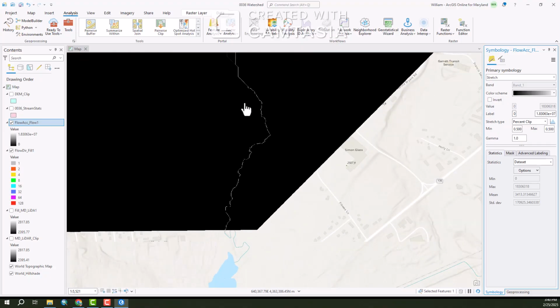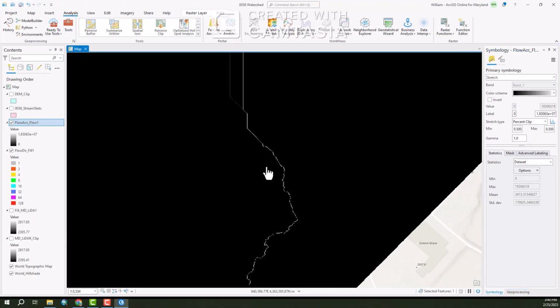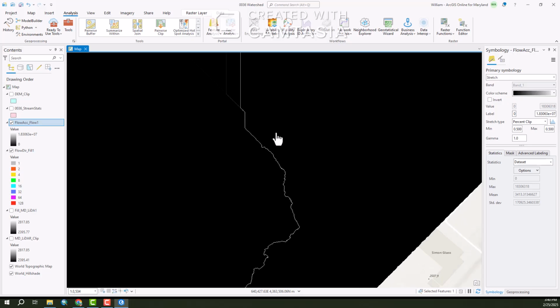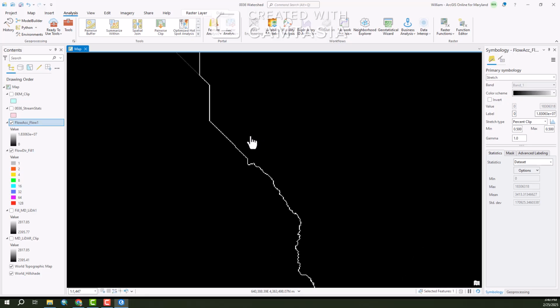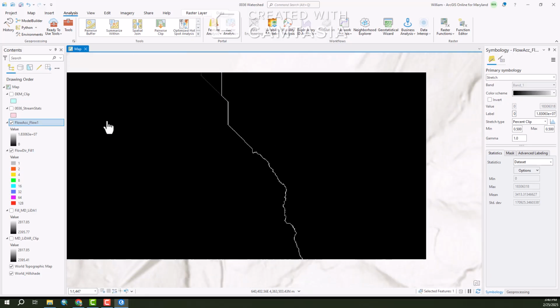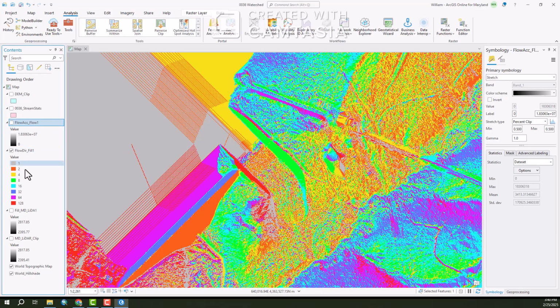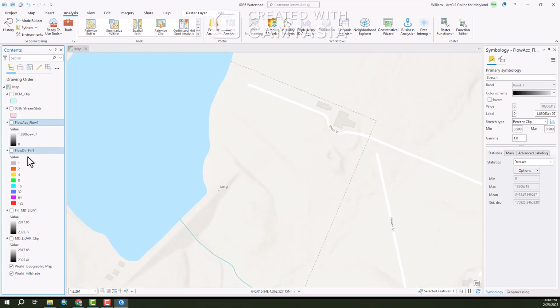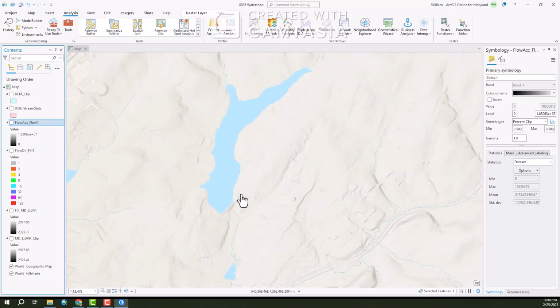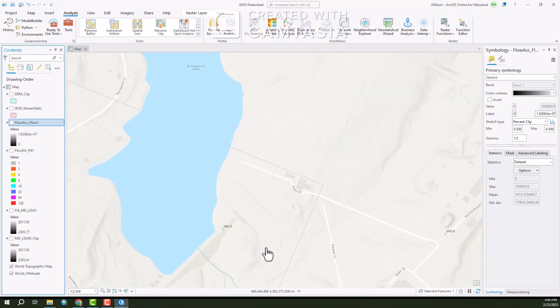We can still get plenty of the information we want. But what I like to do is to toggle the flow accumulation on and off. Let me turn this one off too, because I can see where the embankment is for Broadford, and I can see where the spillway is, and that's based on the topographic map and world hillshade that I have as background images.